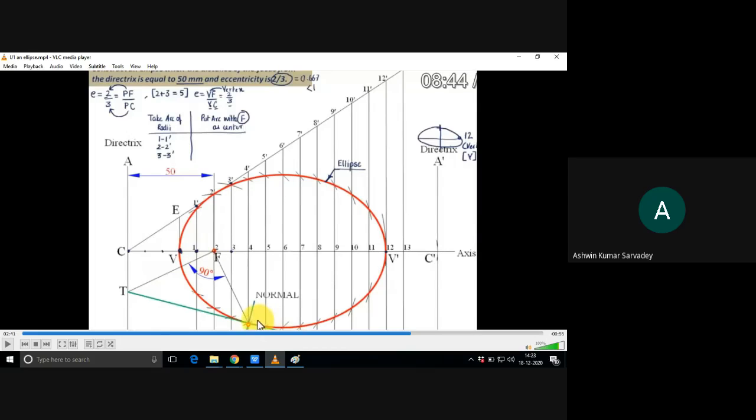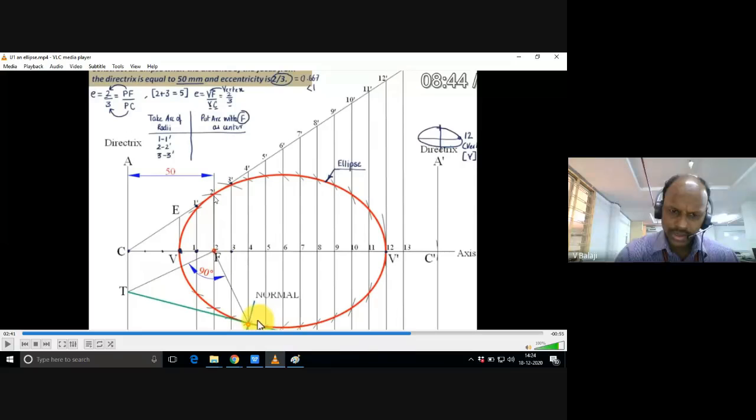So what if we take the point from the line passing through the focus? Yeah, see here, random points I have selected such that we have already done 5 equal parts. After the vertex I have already got 2 points. One is matching with the focus, the other is in between the vertex and focus. You need not take points exactly matching the focus and already existing points. You can choose any number of points at equal or unequal distances, so no issue.